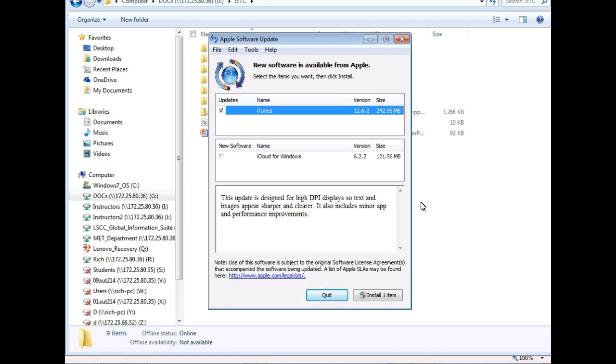And repeatability is how many times it can go back to that spot when it's given a command with a program. Okay, you understand? I might come in and bring it down one time, then go away. That would be accuracy. If I constantly come back to that same point over and over again, how precisely it hits that spot is repeatability. You understand that? What's payload?